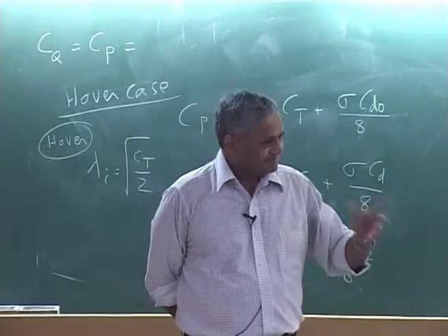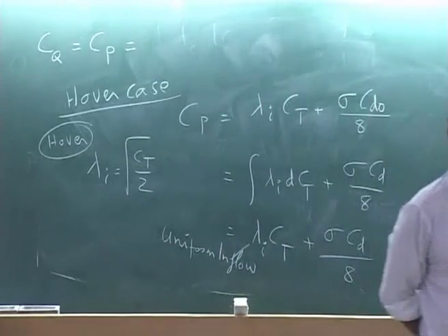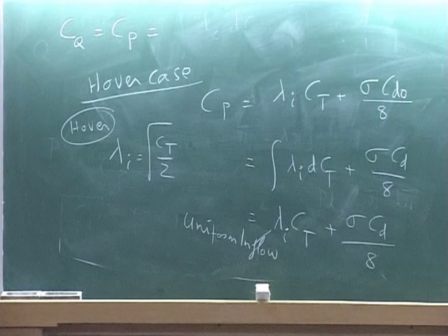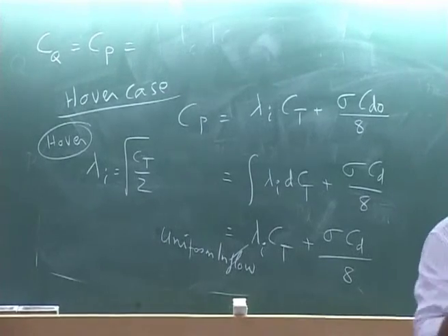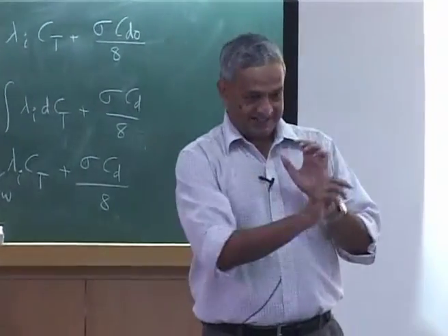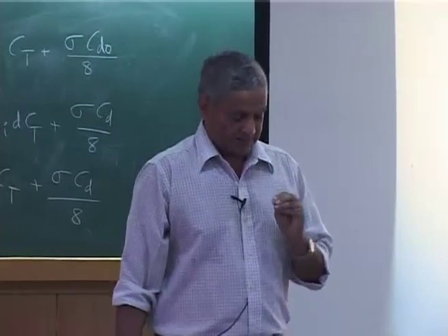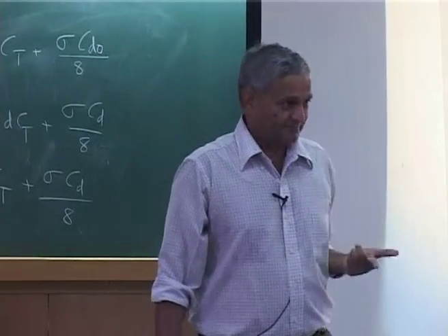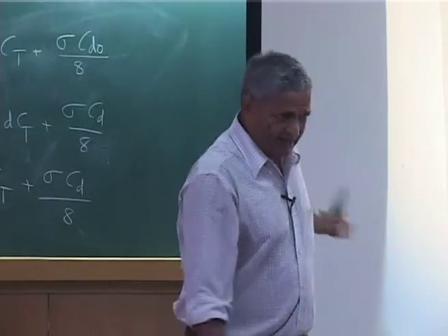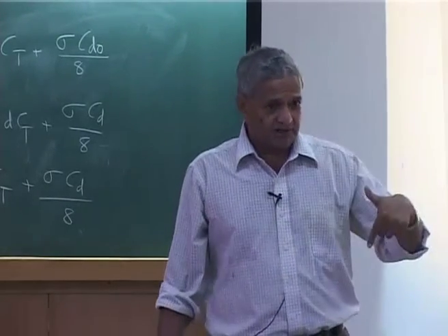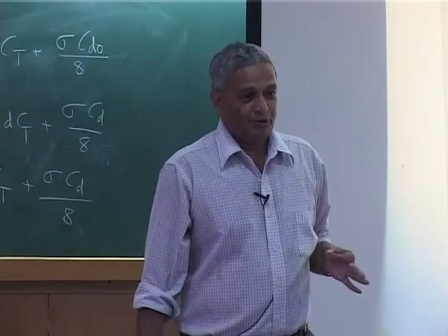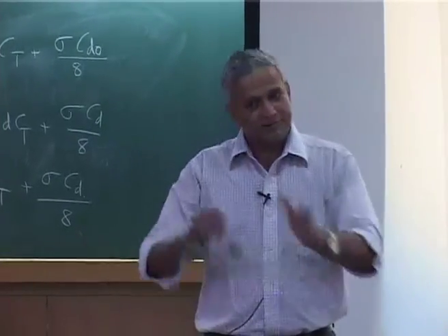And then there is also swirl velocity. Swirl factor, we have neglected it. Swirl, in the sense that you are rotating something, so the flow will also go parallel to the rotor disc. That effect is small, but still it is there. In a propeller, they take the swirl into account. Even here you can do it, but how do you get the swirl? Again through simple momentum theory. I will not go into that, but if you want to know, I have it.